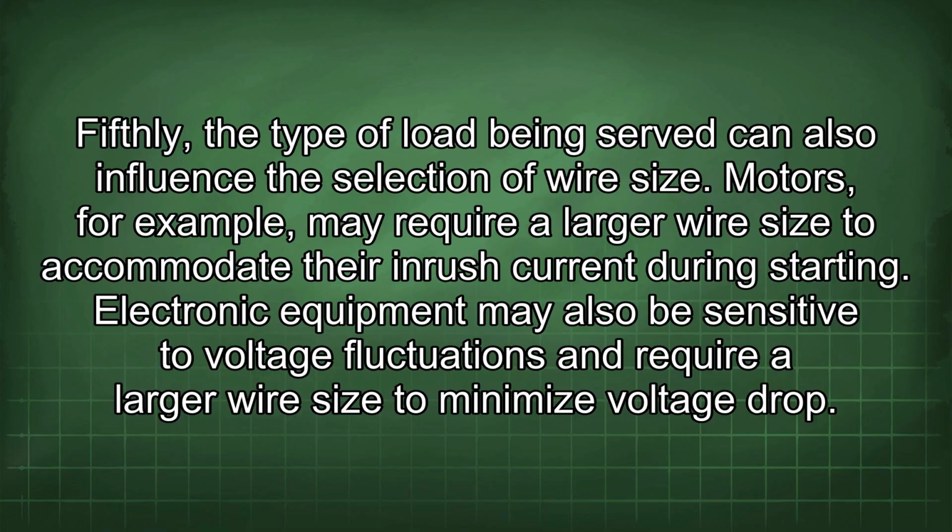Fifthly, the type of load being served can also influence the selection of wire size. Motors, for example, may require a larger wire size to accommodate their inrush current during starting. Electronic equipment may also be sensitive to voltage fluctuations and require a larger wire size to minimize voltage drop.